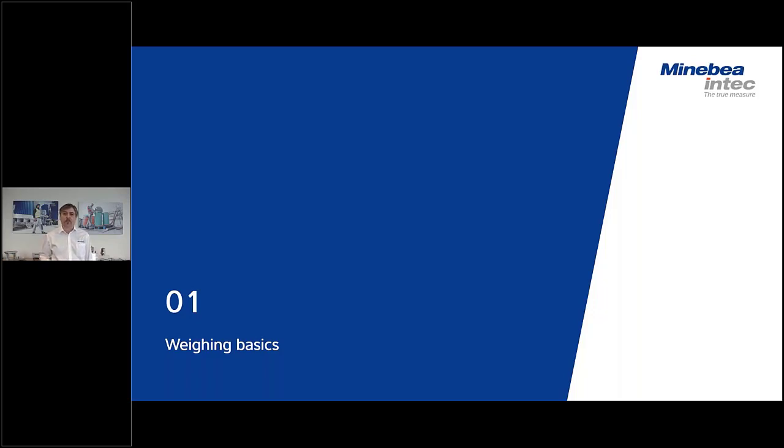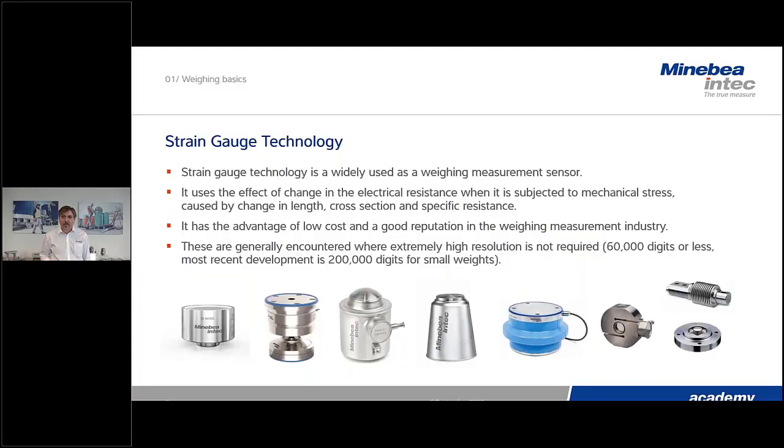First, I would like to talk about weighing sensors and accuracy considerations. The most often used principle of weight sensor, especially in the industrial environment, are strain gauge load cells. These load cells offer an economical and effective solution for determination of weight value. Further benefits are the robustness and durability, even under difficult conditions, and also availability of high capacities.